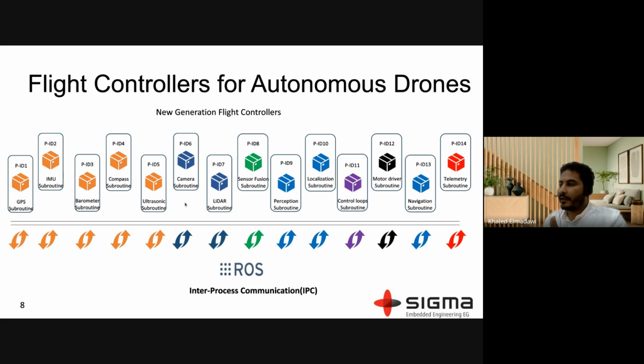When it comes to modularity, one of the advantages of this software stack is modularity and scalability. You can scale it as much as you wish. So, for example, in the state estimation of the drone, you can scale it by, for example, using the optical flow coming from the camera, and all that is required to be added is that the sensor fusion will just take the new state of the optical flow and add it to the fusion states or the observed states.